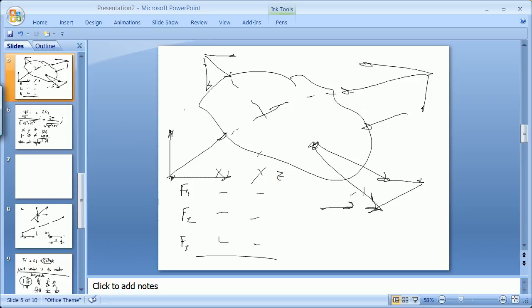All right, so that is how you pull out your scale, and you actually read, and you don't think inches. You measure and put the pounds here and the pounds here. If you're doing that, it might be confusing to mark up actually what the magnitude is. So if you're going to do it this way, there's no reason to actually scale out that vector. That length, that magnitude of that vector is useful if you're doing something like this. But in this case, if you're transferring vectors, sliding them in parallel ways, you don't really need to measure anything until you measure your resultant. All right, that was one problem.